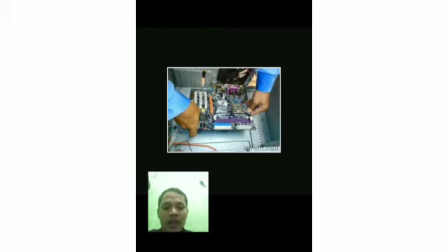If the standoffs have been installed, then you need some tools such as a screwdriver to tighten the screws. Position the I/O panel correctly. Be careful and go slowly when installing it so that the mainboard is not damaged or broken.